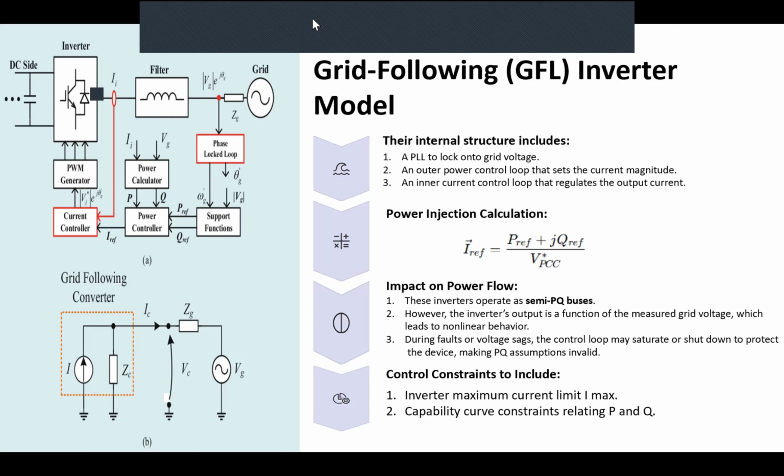So what the inverter does from the power flow perspective, from the power injection perspective, is that it decides the reference current that you have to have, based on the PQ and the voltage at the terminal.